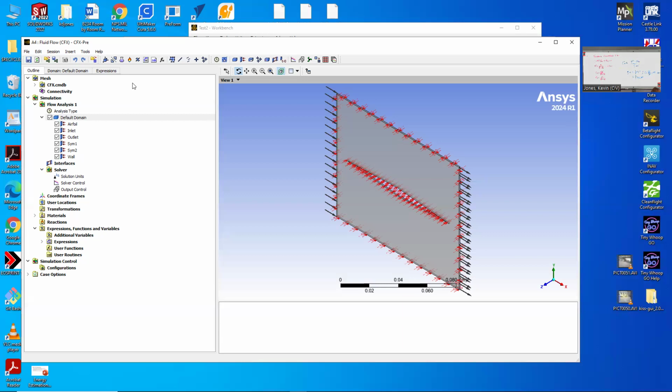In industry, again, it depends. If you're doing a missile design study and you cared about drag, yes, it'll be in there. There'd be no way to skip it. If you were trying to do the control derivatives, like the effect of control surface deflection on pitching moment, you could skip it, because a lot of those are actually potential flow or VLM methods, because they get you close enough.